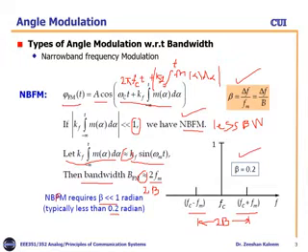You can clearly notice that there are two sidebands. One is the upper sideband, the other is the lower sideband. So it is similar to the amplitude modulated signal, which we already studied. For a narrowband frequency modulated signal, the bandwidth is around 2B, which is similar to the AM signal which we already studied.